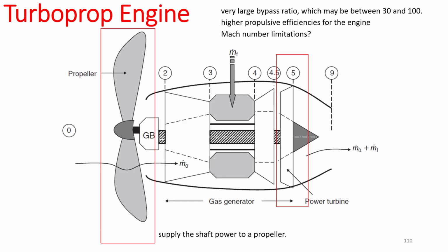Why is this happening? Why do we have this limitation? You don't want the propellers to reach supersonic. Weight, drag. Exactly. You don't want your propeller to reach supersonic conditions, and when your flight Mach number is 0.7, 0.8, you're going to see local supersonic conditions on your blade tips, right? Which is not a very desirable thing.